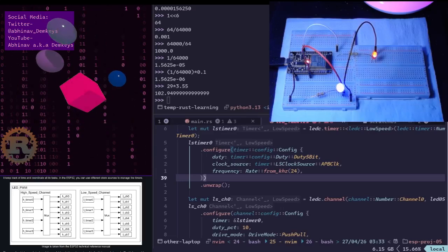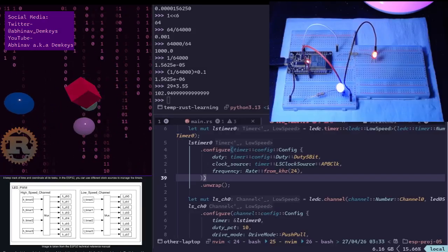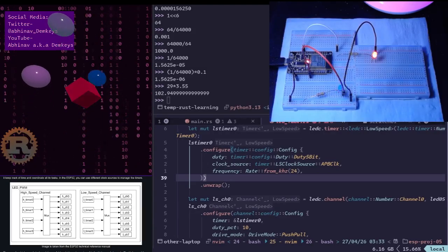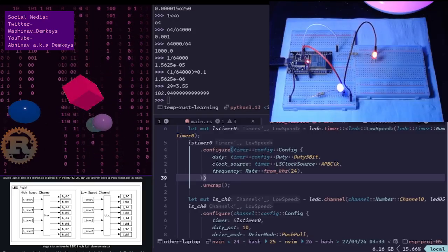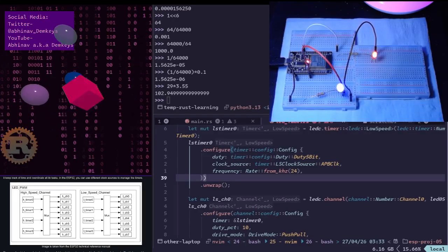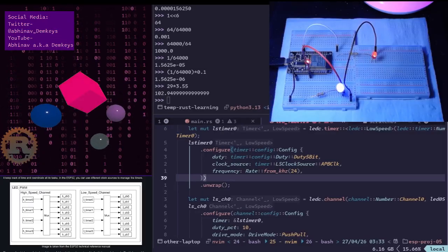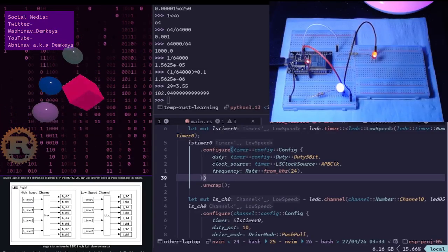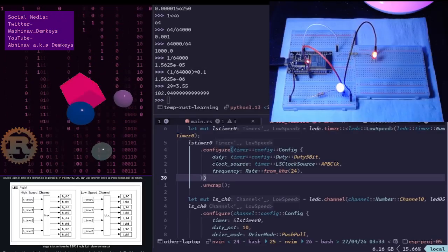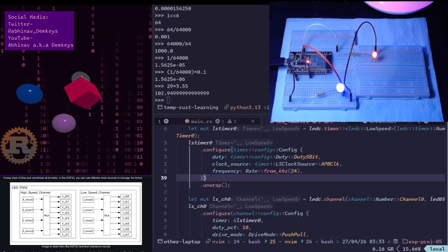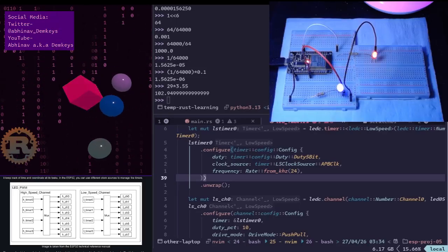On the original ESP32, it supports Bluetooth 4.2 and Bluetooth Classic, useful for connecting to older audio devices or legacy car systems. On the C3 Super Mini, it supports Bluetooth 5.0 LE. I think LE stands for low energy, but it lacks Bluetooth Classic. However, Bluetooth 5.0 offers better range and modern mesh networking features that the original lacks.